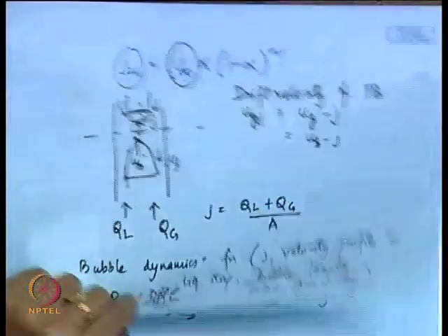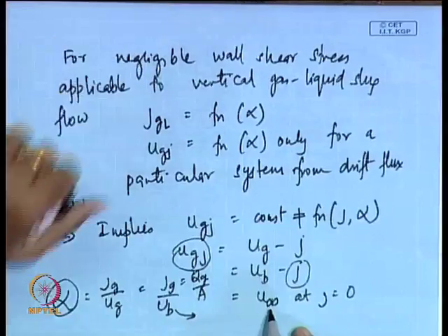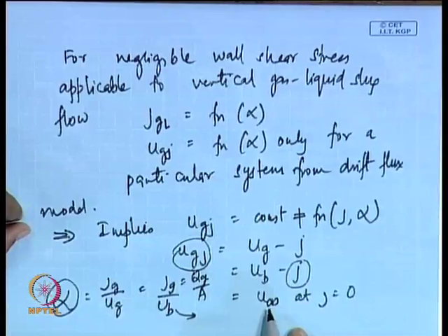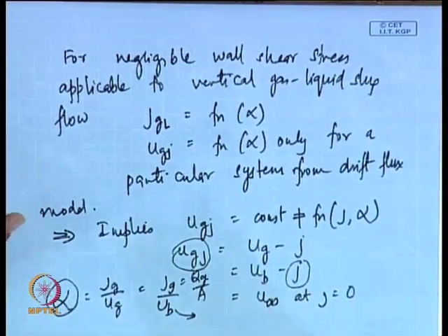If you get confused, you can use some other nomenclature for this. This is the velocity of a single Taylor bubble in that particular conduit characteristics. There is nothing infinite medium here, because remember one thing, in an infinite medium we will not have Taylor bubbles. Taylor bubbles are formed just because the gas is confined or constrained by the surrounding walls to flow through a definite space.